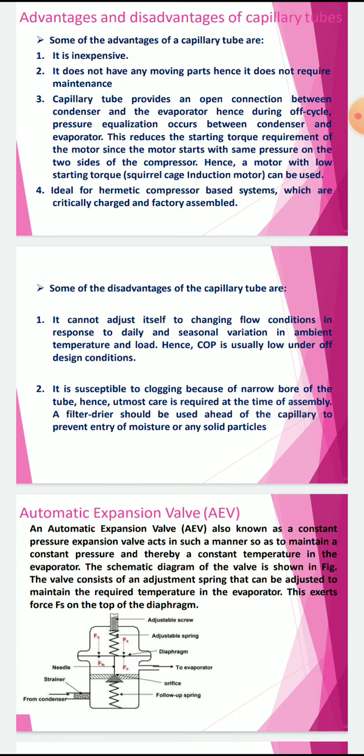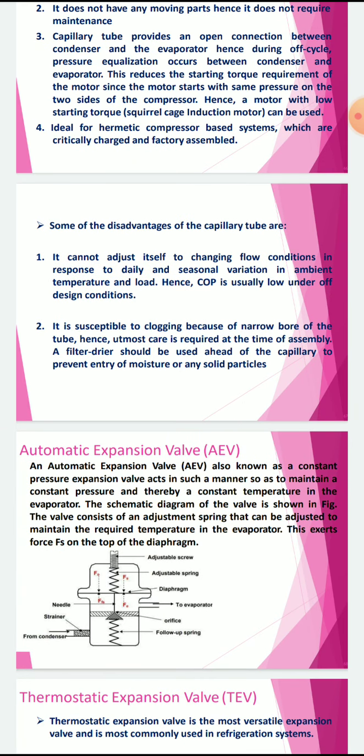Some of the disadvantages of the capillary tube are: it cannot adjust itself to changing flow conditions in response to daily and seasonal variation in the ambient temperature and load. Hence, COP is usually low under off design conditions.